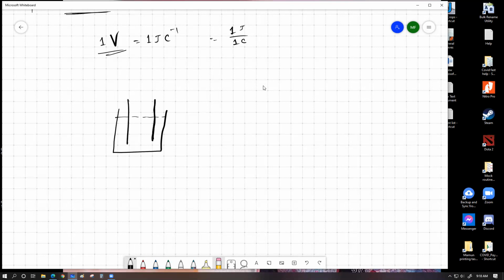These 2 materials react differently with the liquid solution over here, and as a result, one experiences a shortage of electrons. It means the solution somehow pulls electrons out from this one, and it keeps on accumulating electrons onto the other one. The chemical reaction that these 2 electrodes do with the chemicals within this battery basically does this job. That's what you need to understand in the first place. The chemical reaction, by its own capability, accumulates electrons on one of the electrodes and steals electrons from the other electrode. So by default, this one becomes positively charged, this one becomes negatively charged, and naturally they would want to come back to their original state.